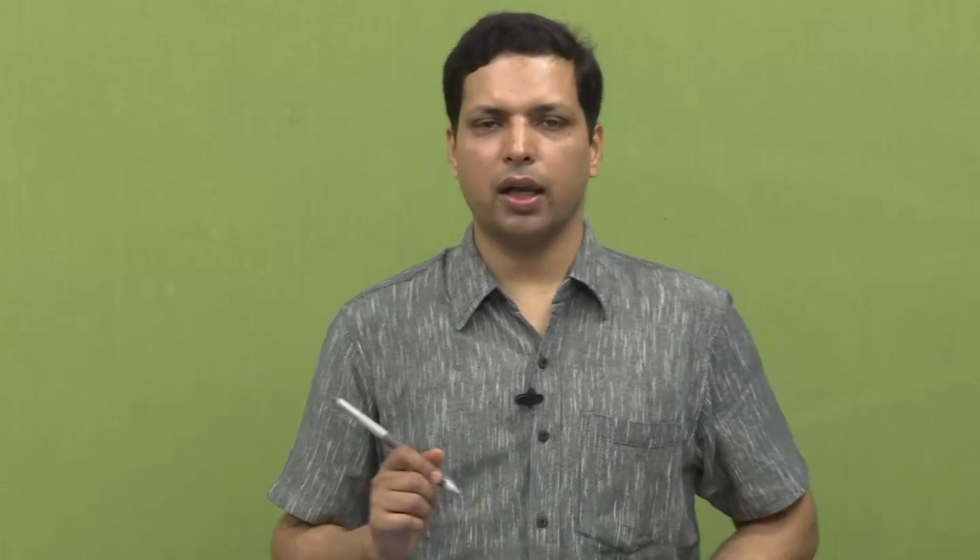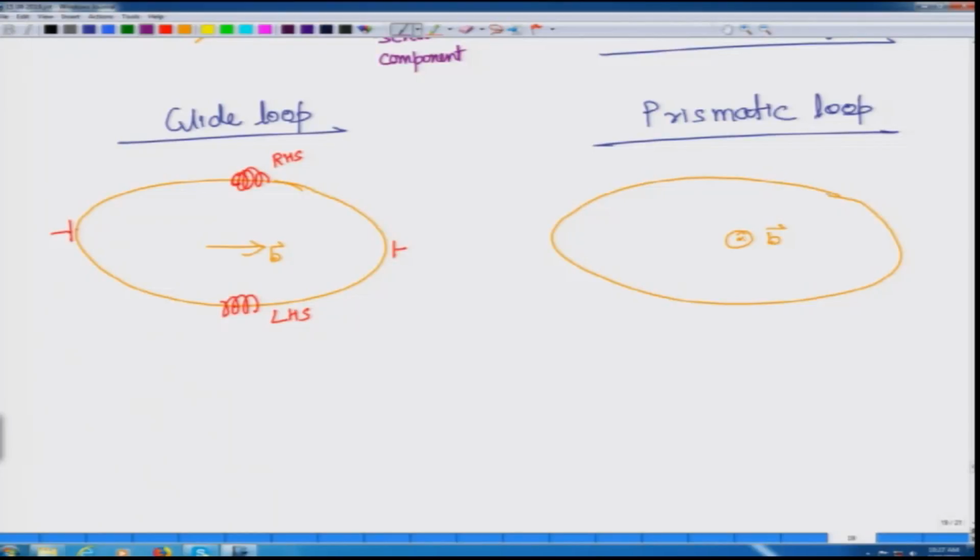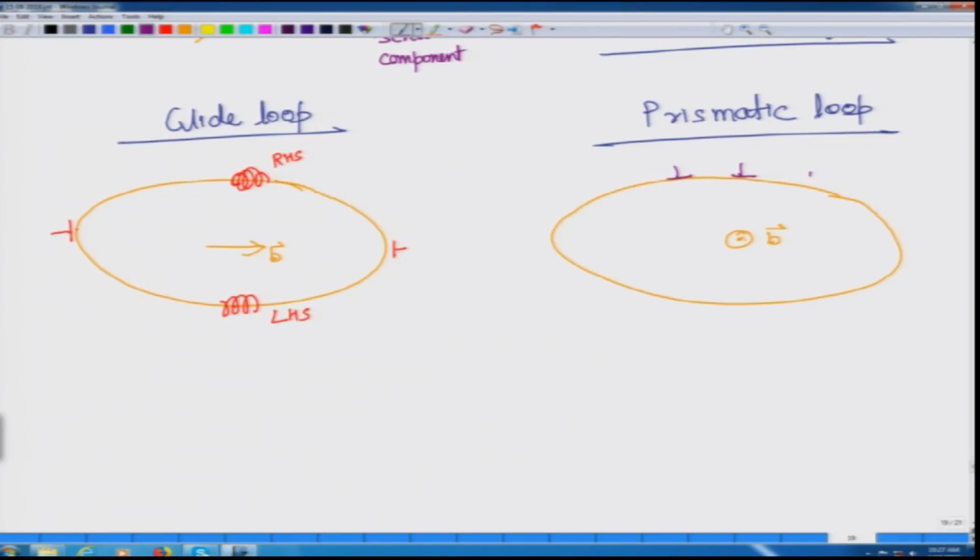Now, how does it look, or how are the atoms arranged here? It is not very difficult if you think about it a little bit. What you will realize is that either you have an extra loop of atoms present, or there is an extra loop of atoms missing over here. So, it is more like vacancies which have condensed in this region. So, these are the condensed vacancies and there is an extra plane all around. So, you can draw it something like this. So, there is an extra half plane, extra half plane.